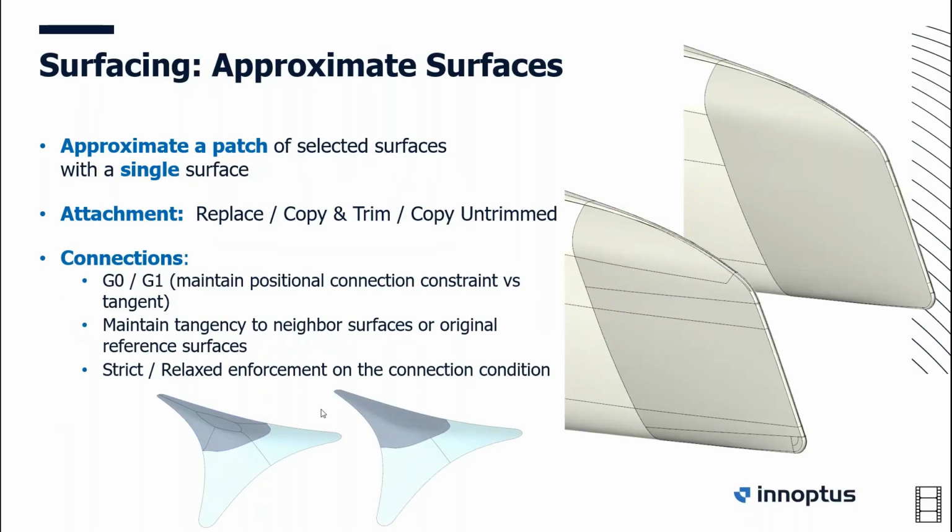This I find a very interesting one. For you guys who are familiar with surfacing, you know that if you create a surface with multiple curves, or based on multiple curves, you also have those connection lines. Those connection lines can be interesting, but can be hard to work with downstream. Sometimes you have some very little lines on a radius that annoy you or that limit the feature in building.